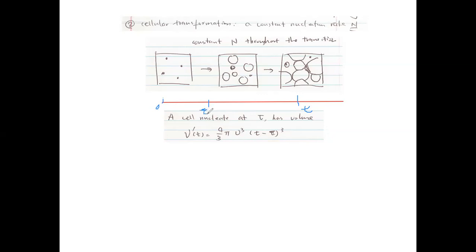Okay, I'm writing this. So now if this nucleus forms at 0, in the beginning of the process, and I make an observation of this nucleus, what is the radius that I'm going to see for this one? The radius is going to be v times t, right? Because this nucleus formed in the very beginning at t equals 0, and now it grows for all this time. So the size of that nucleus is going to be v times t. Is this clear to everyone? I hope it's very clear.